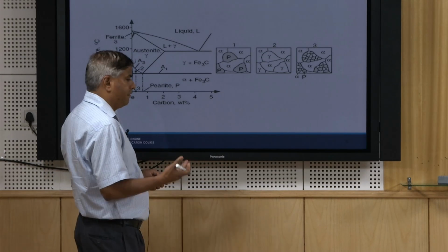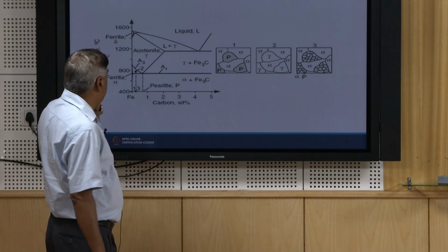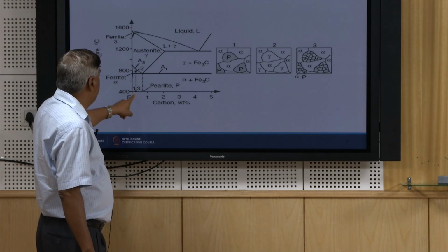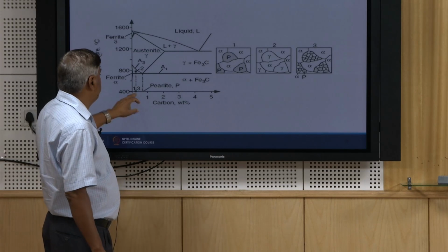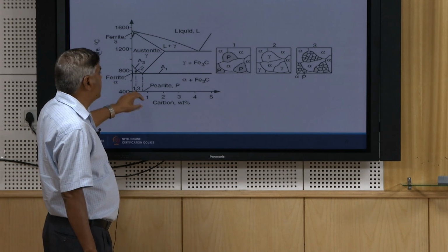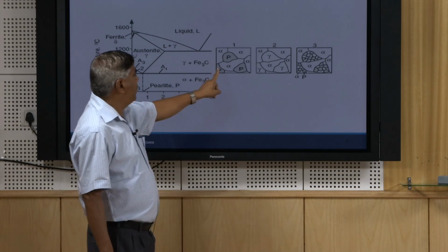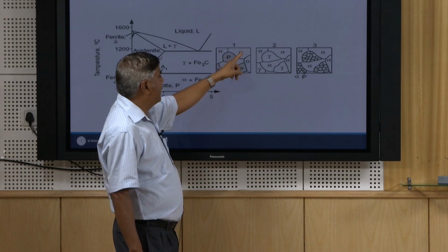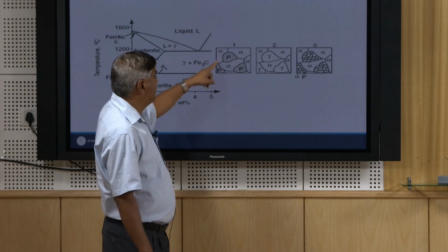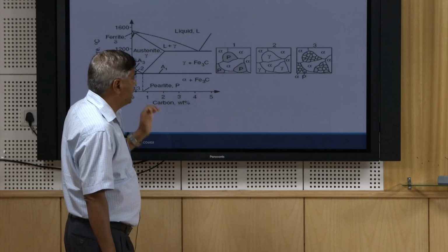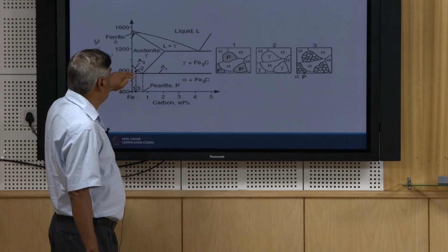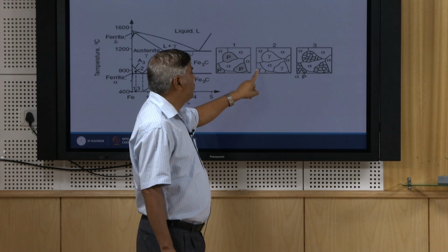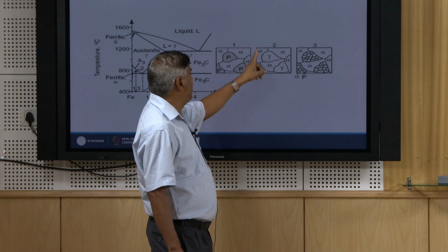As per the composition it will have different phases. If you look at the base metal, say a typical steel, corresponding to 0.3% carbon steel at points 1 and 3, at point 1 it has ferrite and pearlite. So the ferrite alpha and pearlite are the gray shaded areas. When it is heated to point 2, the pearlite will transform into austenite, while the alpha will remain as it is.